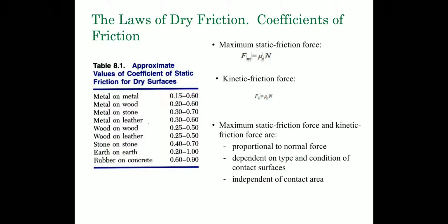It depends only on the normal force and on the conditions of the contact surfaces, the roughness of the contact surface, and is independent of contact area. So frictional force is not dependent on contact area, but it depends on the normal force and also on the surface conditions.